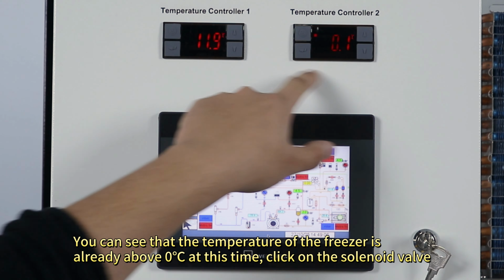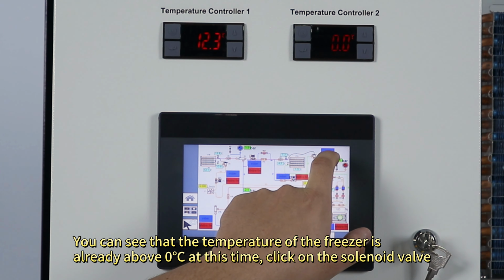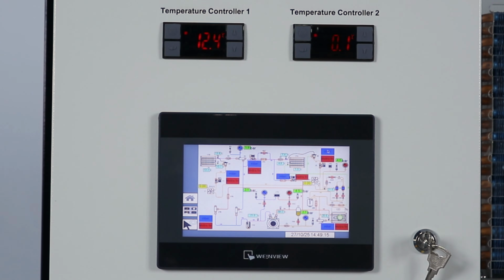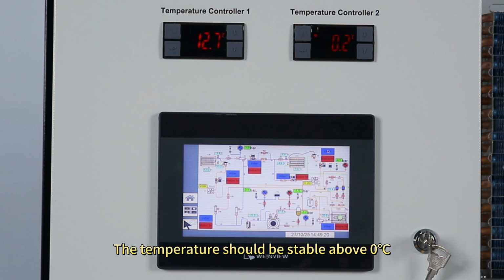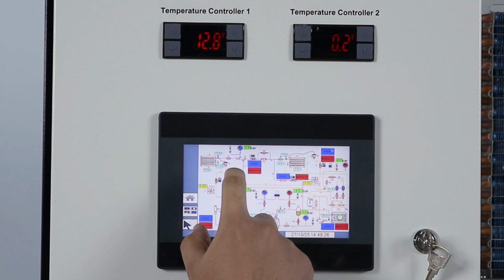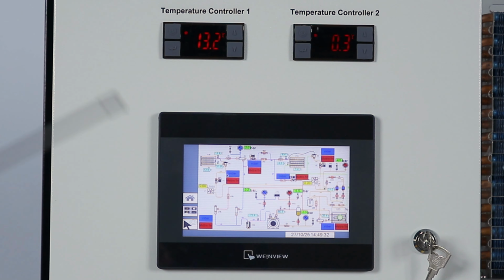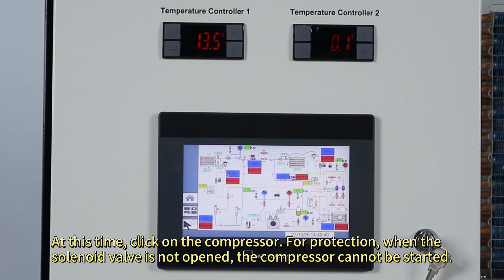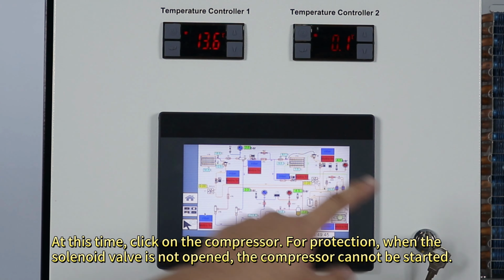You can see that the temperature of the freezer is already above 0 degrees centigrade at this time. Click on the solenoid valve. The temperature should be stable above 0 degrees centigrade. You can see that clicking on the solenoid valve has no effect. You need to wait for a while to run. At this time, click on the compressor for protection. When the solenoid valve is not opened, the compressor cannot be started.